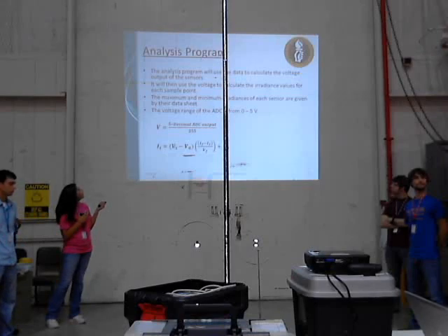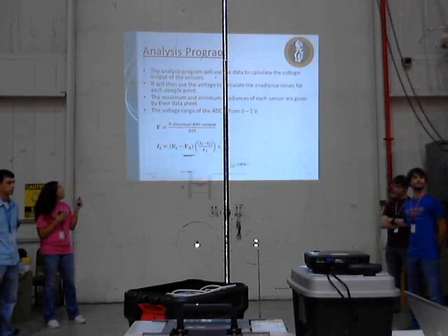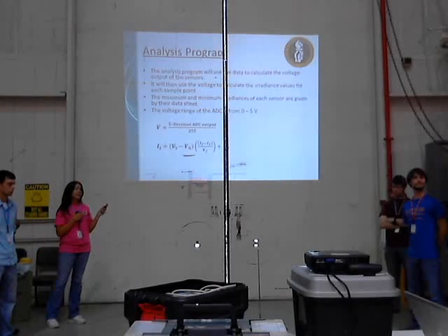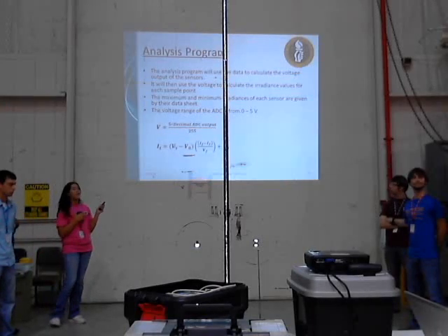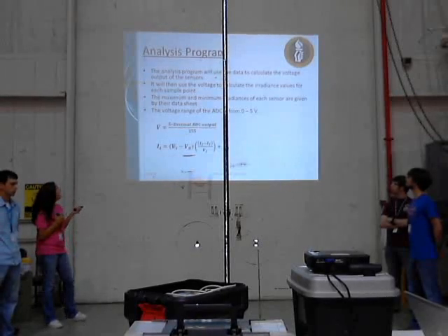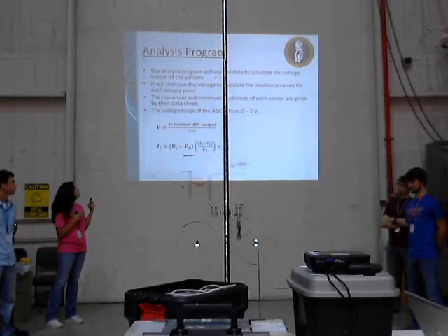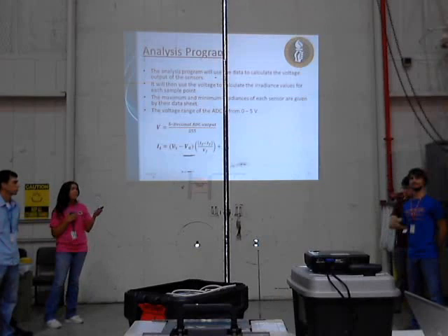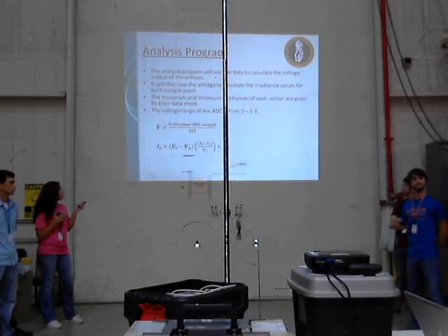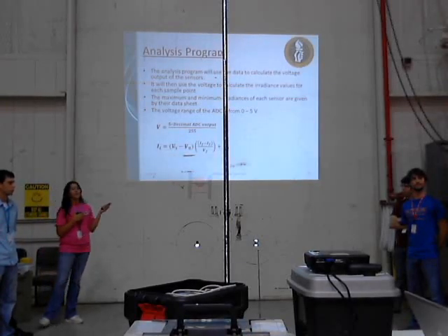During the analysis program, I'm going to use a program in MATLAB and interpolate the UV over time, and I'm also going to interpolate the altitude over time, and it will parametrically graph those two together to graph UV over altitude. We have to first get the decimal or the voltage from the ADC, and we'll use the decimal value that we get to find the irradiance for each UV. We have a formula that we will be using with the voltage to determine our irradiance for each one.